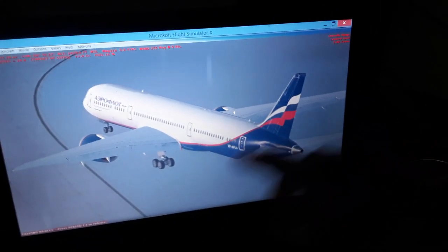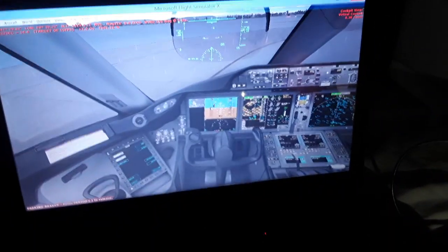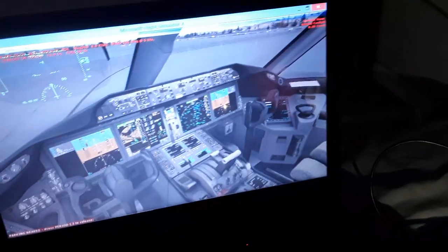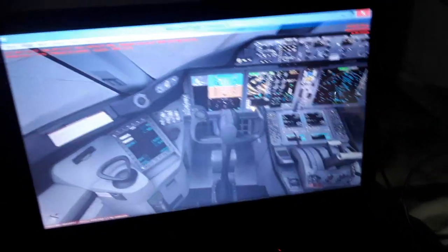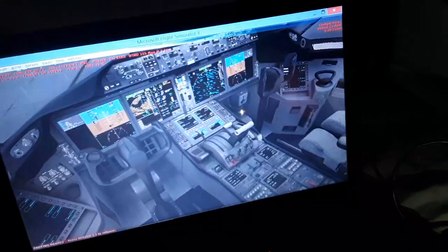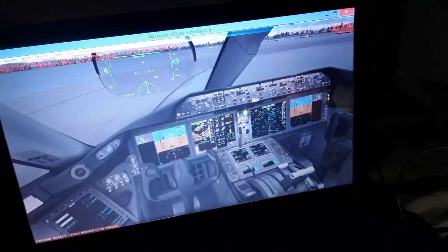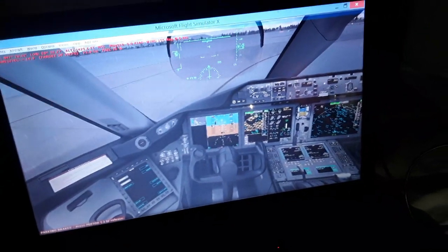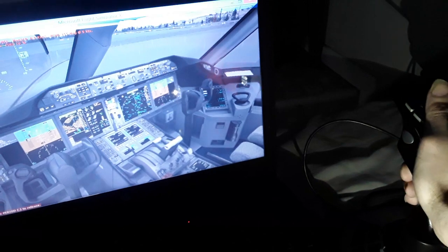We can also use the rudder pedals, the rudder, and the nose wheel steering, the tiller, on the ground. We can deflect 76 degrees left to right with the tiller, and it decreases as you advance the airspeed, like at 45 knots it decreases to 7 degrees right or left deflection of the nose wheel.